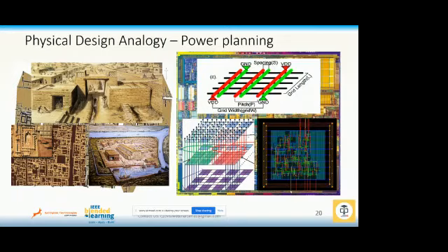So once you have planned everything, then you lay it out in the layout so that all components get proper power supply. And you also have to do IR drop analysis to ensure this power grid is intact.